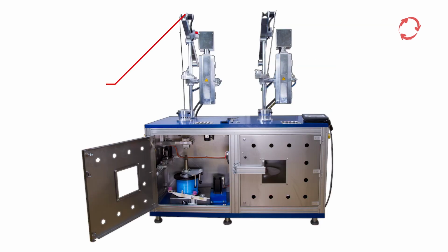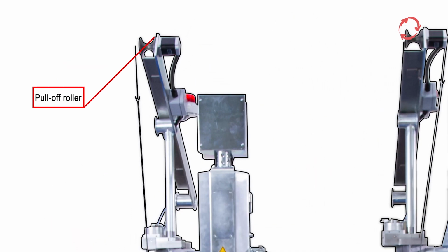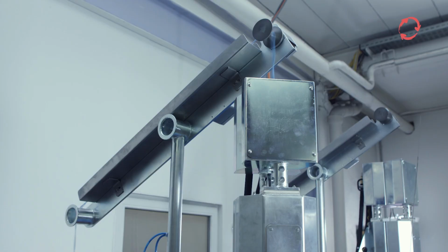The driven pull-off roller is located above the upper end of the winding mandrel. Depending on process speed and preset pull-off value, the roller pulls the spiral up from the spiral mandrel, and from there the spiral moves down into the spiral can via a downward-sloping guiding track, slide. The spiral can also be wound 1 to 2 times around the pull-off roller in order to increase the tensile force.